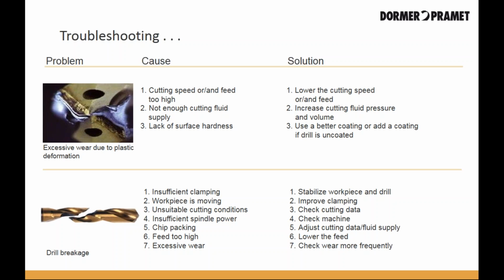Solutions: stabilize the workpiece and the drill, improve the clamping, check your cutting data, check the machine, adjust your cutting data and fluid supply, lower the feed, and check the wear more frequently.